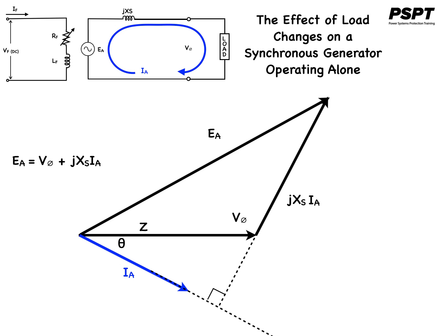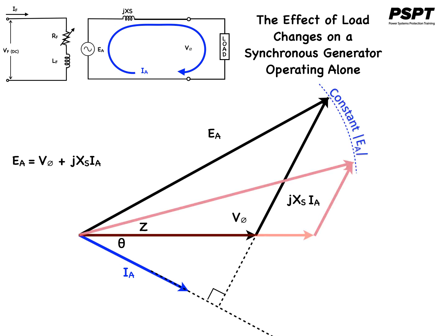If these constraints are plotted on a phasor diagram, there is one and only one point at which the armature reaction voltage can be parallel to the original position while increasing in size. The resulting plot is shown here.